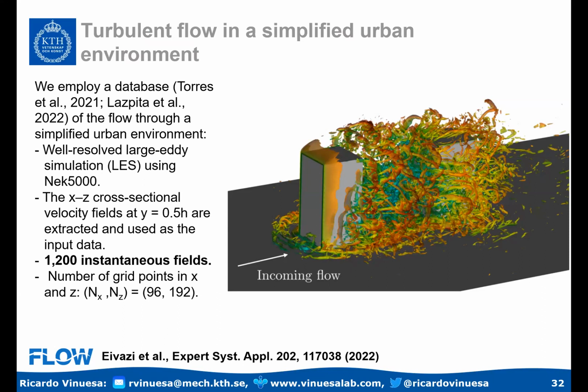autoencoder model is trained, evaluating it is very fast. You don't need to run the simulation. You can integrate it in time super easily. It's very cheap. And with POD you would only retain a few of the large scales, but with this you can really retain a lot of the details. So I think in these multi-fidelity frameworks, autoencoders can become an integral part of those methods. Thanks so much. Thank you for the questions.